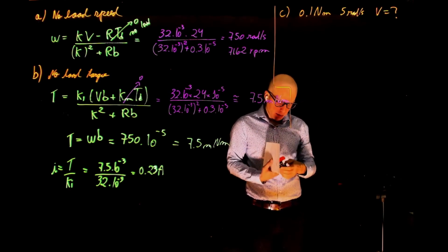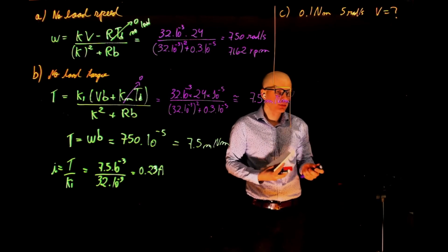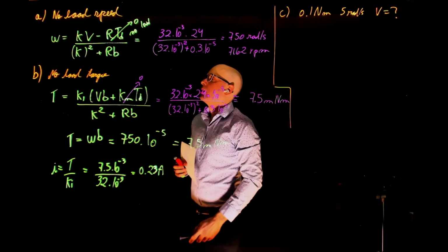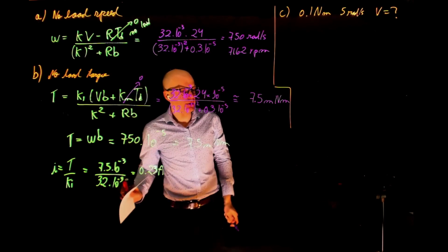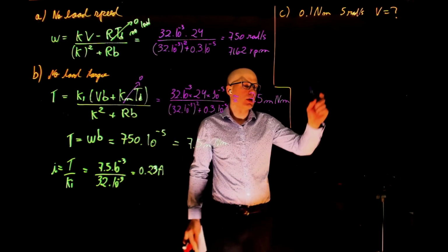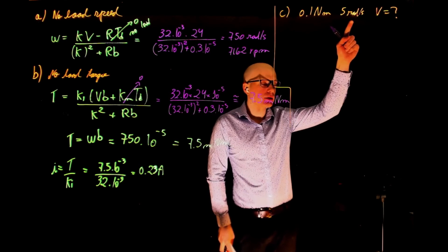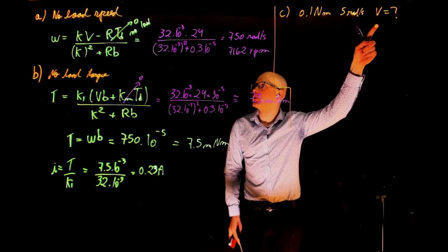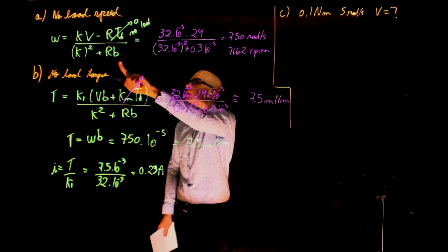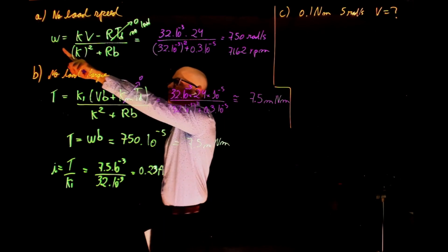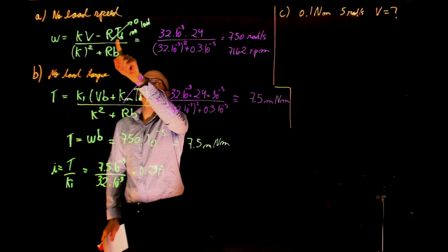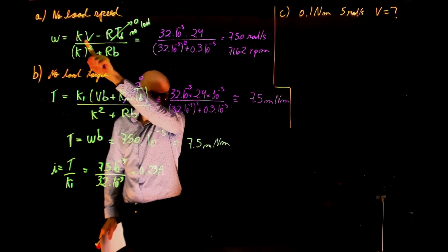How do we do that? So here we have the input voltage. We want the steady state values. Now we have this load and this speed. What is the required voltage? Well, we can first look at this expression and use it now because we know omega, we know TD, we can calculate V.